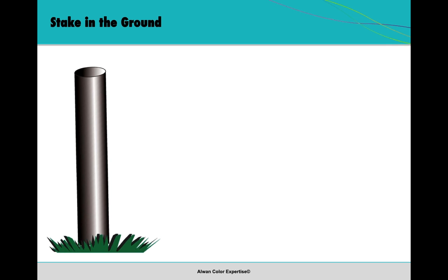You can disconnect just by hitting one button. You can disconnect the eXact from scanning mode and do spot readings anywhere on the sheet, and then go back and say reconnect and do the strip again. So from a productivity standpoint, it's out of this world. I would guess most of you, if you're still using handheld clicks on a press, you'll see an ROI on that in weeks, not months, weeks. So that will ensure that your press is printing to standards better.